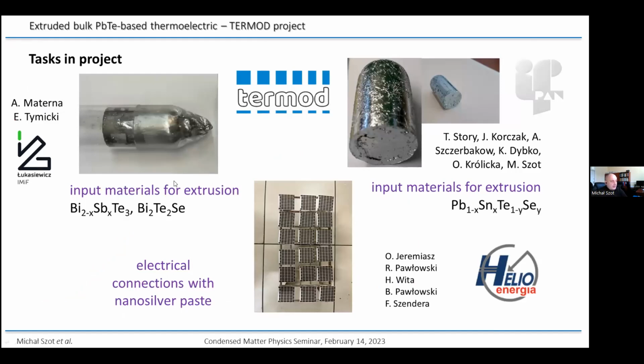Our institution and Institute of Microelectronics and Photonics task was preparation of input materials. In our case, it was based on lead telluride, which was synthesized from elements with not high purity, and by the fast Bridgman method, all of this to decrease the cost of the material.